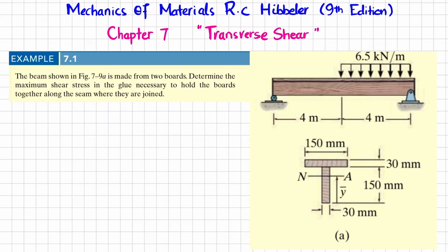The first step is that if I remove this roller support at this point, we will have a reaction force. Let this reaction force be R1, and if you remove this pin support at this point, you will have reaction force R2. Let this be point 2 and this be point 1. So first we will find R1 and R2 by using the equations of equilibrium. What are these equations of equilibrium? The first equation is that the sum of all moments acting about point 1 is equal to 0, taking the counterclockwise moment as positive.